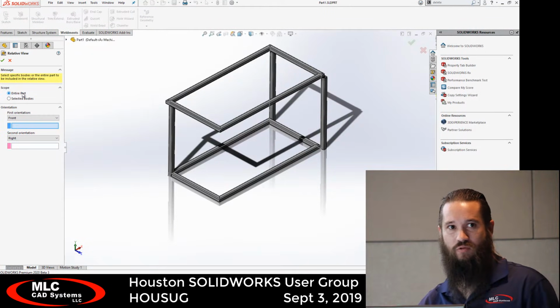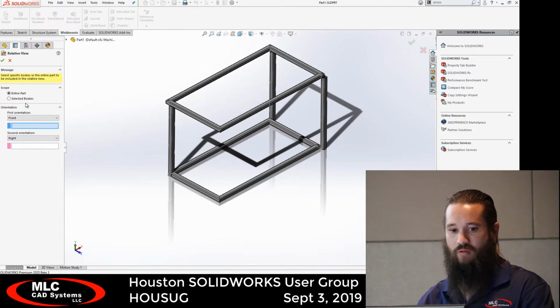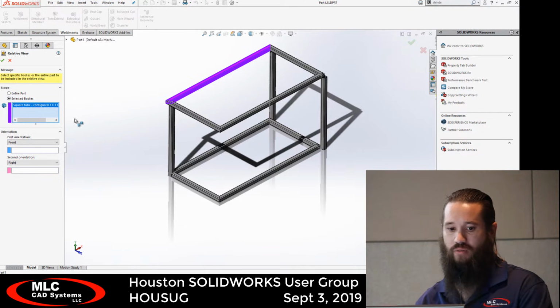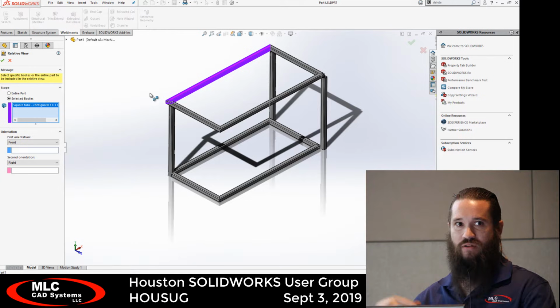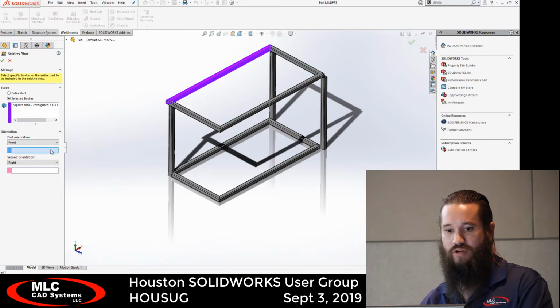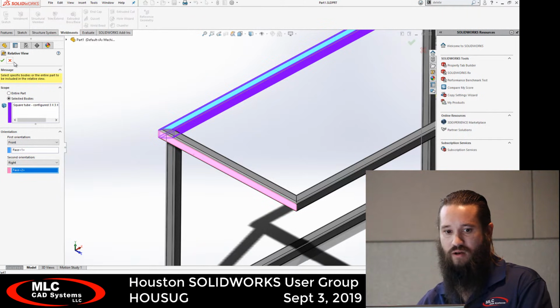And instead of saying we want it in drawing view relative to the model of the entire part, we want a model view just of selected bodies, and that's how we get just individual detail item drawing views on our print. Because these things can be crazy 3D sketches off at weird angles, it may not be in the same orthographic projection that we want our main part to be in. So we can determine a new orientation from here just based on the body. And you can even pick views that aren't part of that, or edges, faces that aren't part of that body.